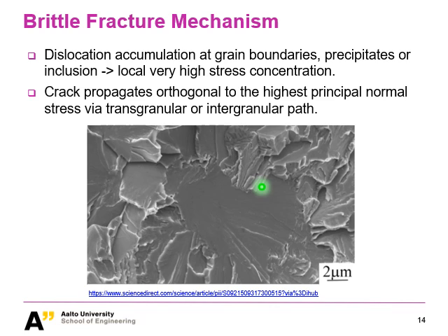Here I'm just zooming in on the surface. You can see this is the brittle fracture, and the crack is definitely not that flat when you look at it microscopically. But what you can see is that it is very clean, so the material is almost like cut into two parts.